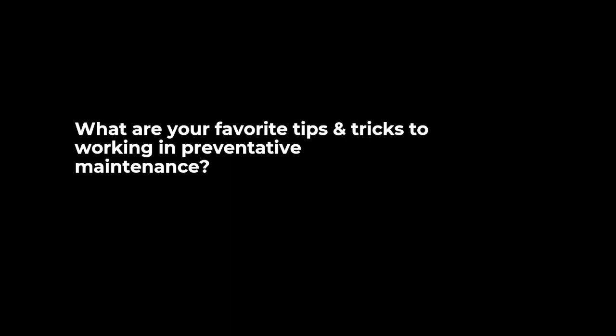Now, is that piece of equipment very critical to you? If it is, then you're catching it too late on the curve with respect to temperature. And you want to catch it much higher, so you have more lead time to actually work on that piece of equipment, or have a replacement or a substitute asset for that, like what Eric mentioned in his case, where they had time to act on that asset and come up with a solution for it.